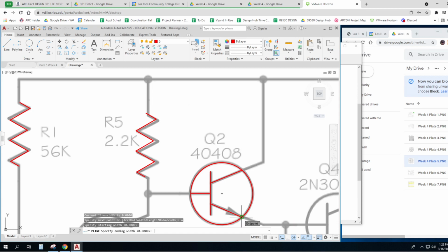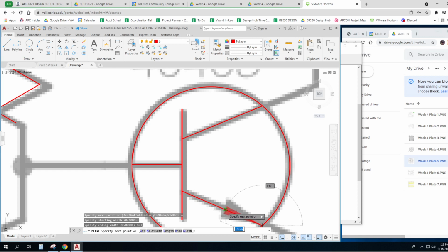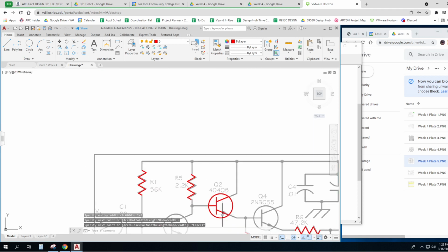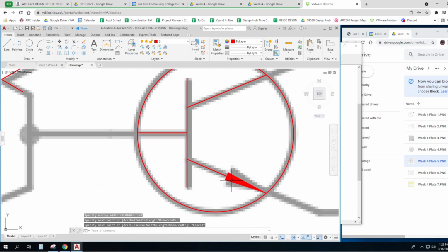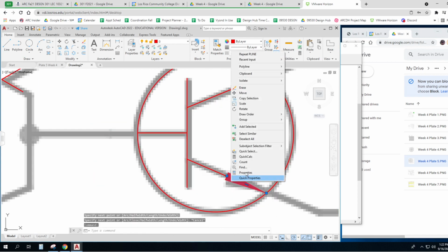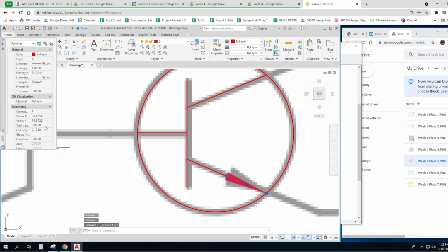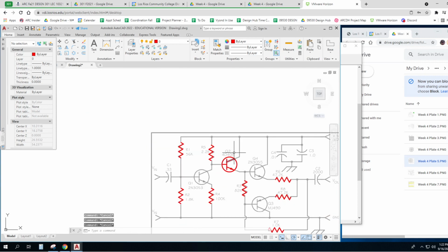And it's going to go to maybe, I don't know, maybe an 1/8. And now I have an arrow. And if you don't like that width, you can go over to the properties and you can change it. Isn't that the coolest thing? I love AutoCAD because if you do something, you can always go back and change it.